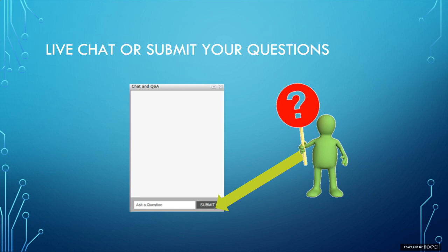This is Neil. I'll start it, and I'll ask Werner if he has anything to add. But from an over-design standpoint, there's a couple things to consider. Werner said this already about no bypasses, and he also mentioned backups. So from a certain standpoint, dryers and filters, when we talk about downtime, we usually talk about 100% redundancy. So if you have, let's say, one dryer, whether it be desiccant or refrigerated dryer, you have one that's sized for the entire demand.